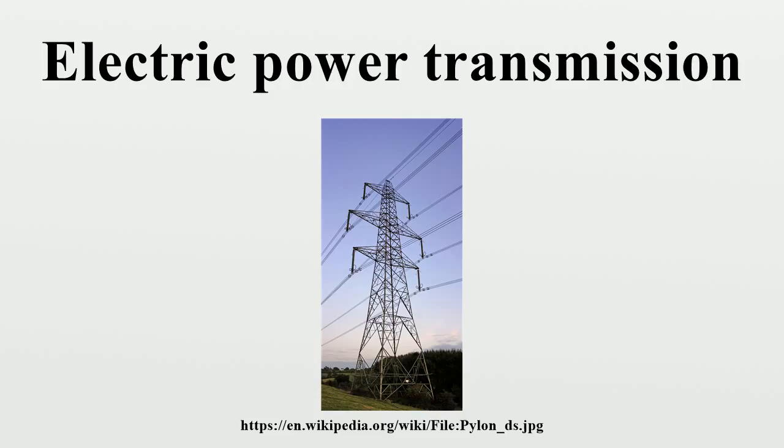Underground cables take up less right-of-way than overhead lines, have lower visibility, and are less affected by bad weather. However, costs of insulated cable and excavation are much higher than overhead construction. Faults in buried transmission lines take longer to locate and repair.